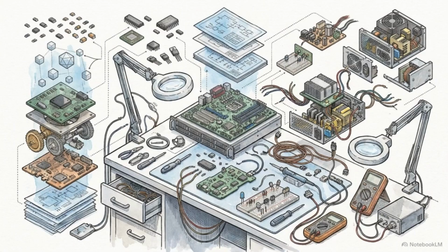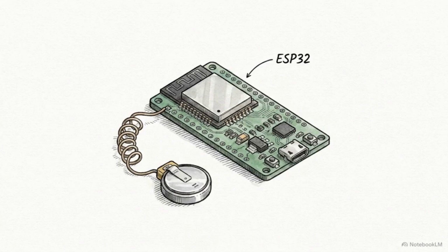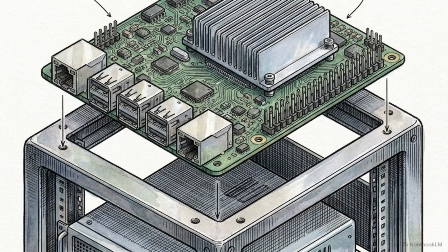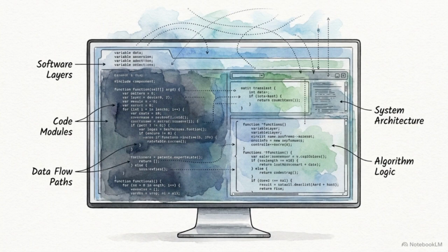The hardware required depends on the complexity of the data. Lightweight microcontrollers, like the ESP32, run simple continuous C or C++ loops. They are highly efficient, designed specifically for low-power processing tasks. Heavy edge processing requires a more robust setup, like a Raspberry Pi. These act as complete microcomputers, requiring full operating systems to execute complex Python scripts and handle larger data loads.